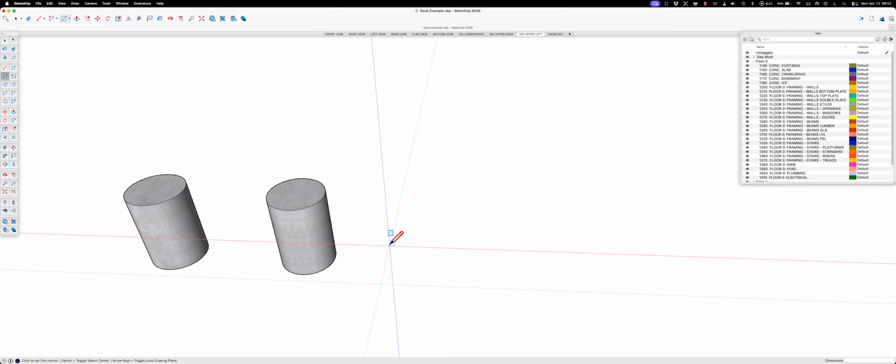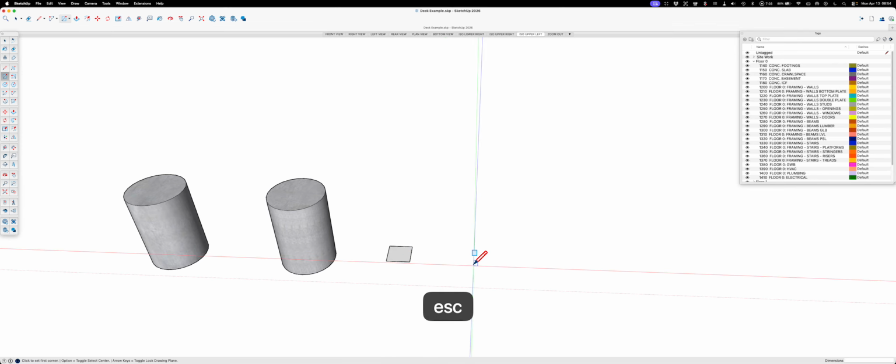So if you click and let go, and then you drag, and while you're dragging, you look to the right, and there's two sets of numbers. Let's say you were going to do something that's rectangular. When you look down there, one of these numbers is 4'9", and the other one is 3 13/16 inches. So you can tell right away the first number is going left to right. And that's something to remember. But for right now, we're just going to go 5.5, comma, 5.5, enter. You want to be precise like that.